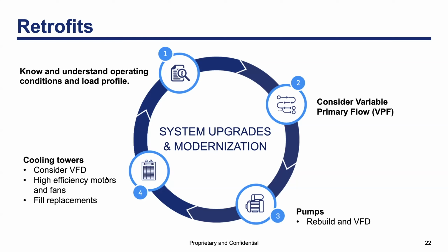But always contact the chiller, the pumps, and the cooling tower manufacturer and ask for these limits. Sometimes in a chiller plant, let's say three constant speed centrifugal chillers, we can apply diversity and install VFDs in two of them, while keeping the third chiller at constant speed. The main idea is to handle the peak load with a constant speed chiller and the partial load with the ones with VFDs. And this is just an example of many variations that we can have in the field. But once again, it all boils down to existing conditions and requirements.